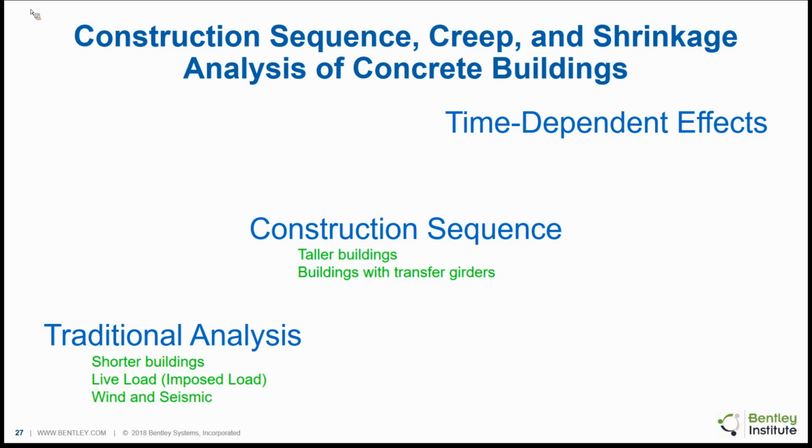Are they acting as a bridge to keep that transfer girder from deflecting more, or are they merely acting as loads on the transfer girder? And the construction sequence analysis will give you very different results on the member forces in the transfer beam. So I would consider it for a building with transfer girders.